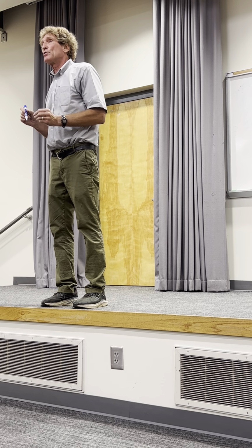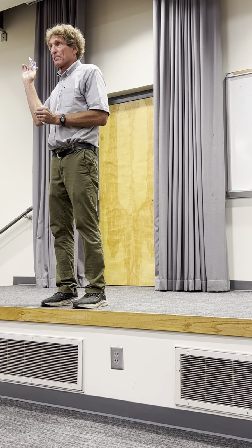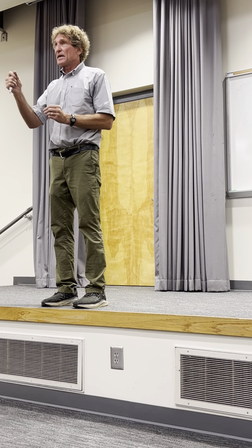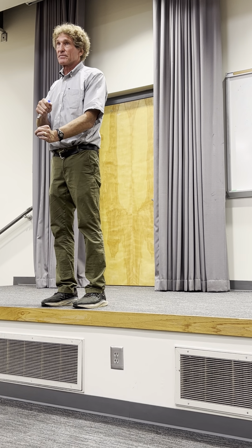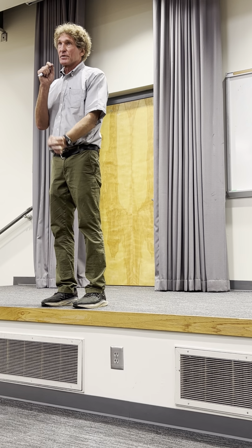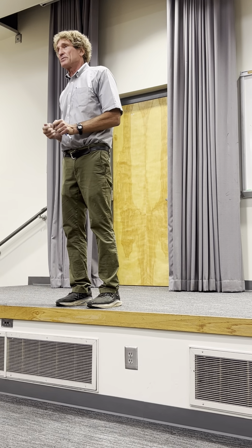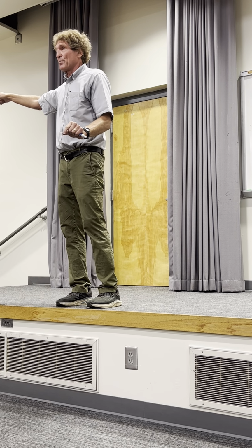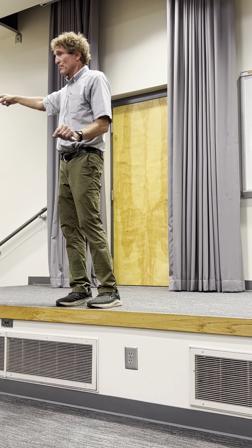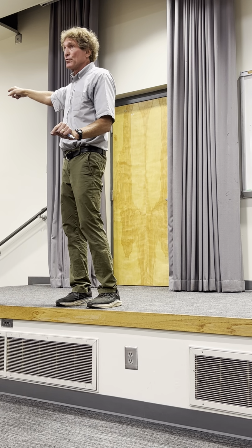Now, an electrical earth ground, have you heard that? Anybody else heard of an earth ground or an earth grounding rod in here? That is a thing that you're supposed to drive into the ground. It's a solid piece of copper steel thing with a certain diameter, a certain distance in there, and when the resistance between that point and another point is measured, and I forgot how far away the second grounds are, it has to be below a certain value for it to be considered a true electrical ground.